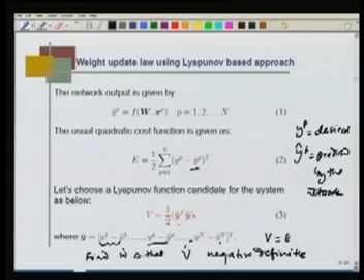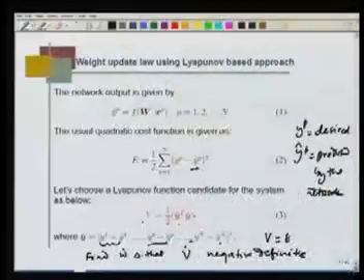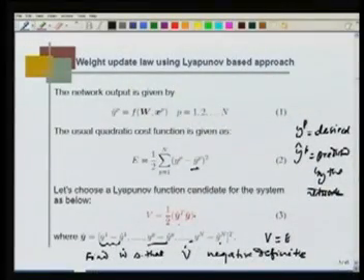Okay. That is how we deal with a nonlinear function. You can easily see this is a nonlinear dynamics, because V is a nonlinear function and y hat p is a nonlinear function of W, and I am now saying W dot, that is, the evolution of W, follows a certain dynamic law. So, then this becomes a completely dynamic equation, and if V dot can be negative definite, then I can say the W dot that is given to me is a weight update law that guarantees stability.